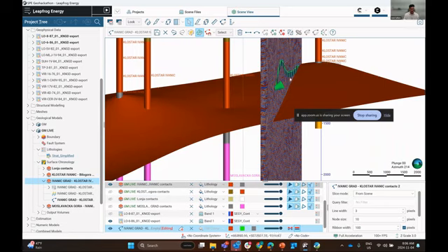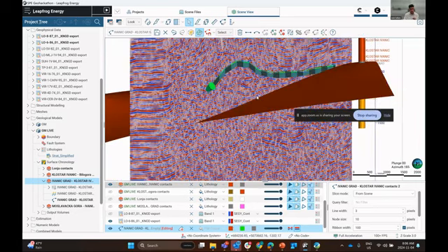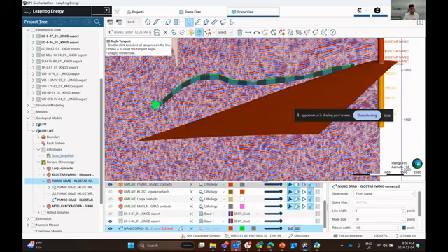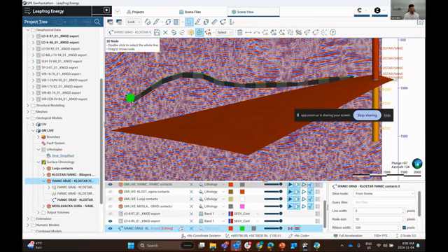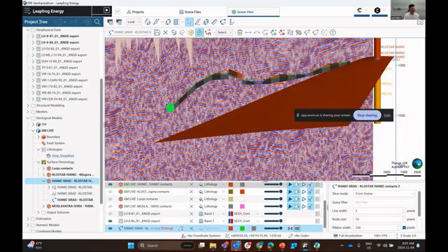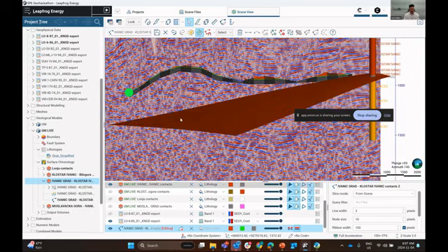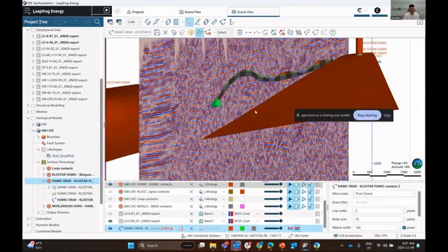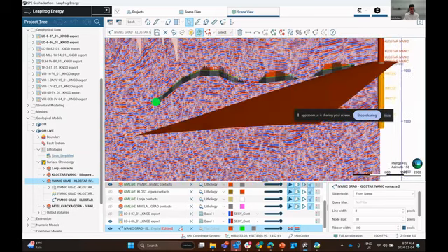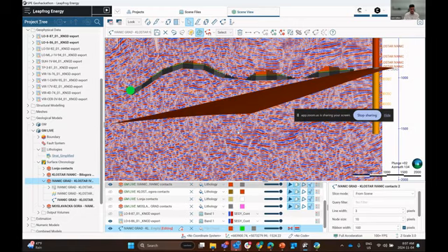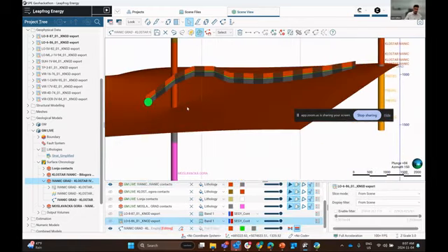So this increases the ribbon, which shows us the polarity associated with this polyline, and also the cone, which shows us the direction. The tangent cone can be adjusted by left clicking the tangent cone or the directionality of this tangent cone and pressing A, that's A as in Alan, on your keyboard. So if you left click this cone and press A, you can see that the directionality of this polyline gets adjusted. I'm going to turn off that seismic line shortly.